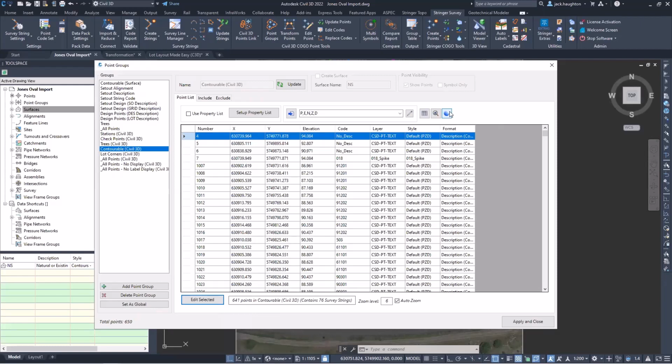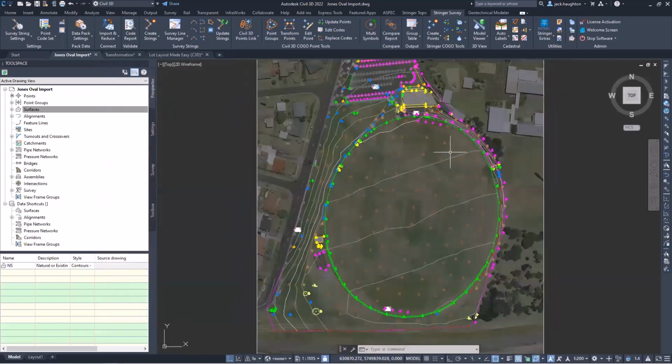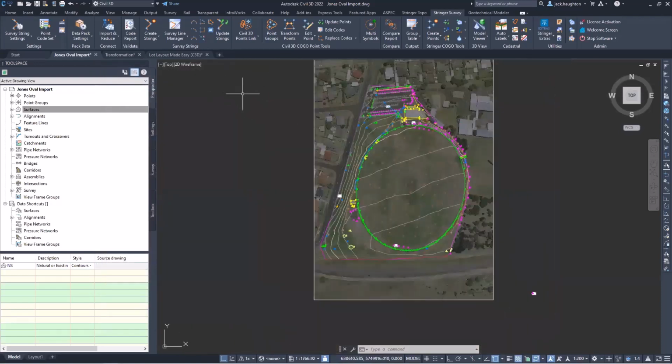Now the export KML, I won't open it here, but I will just describe it. The KML allows you to export all of your line work and your point information out to things like Google Earth and Nearmap. It can then be used to set up an online database where you're able to pull that information back from Google Earth into Civil 3D and be able to find all of your coordinate information for your instruments and such. I do recommend looking into this, as having a digital database to work with could be a really cool thing to have for your future surveys. Say you did a job over in this area, you could type that address in, see that you've done a job over here, find the instrument information, read it into your survey, and you're good to go.